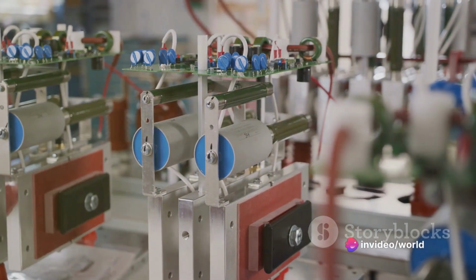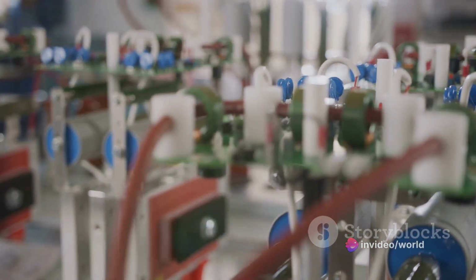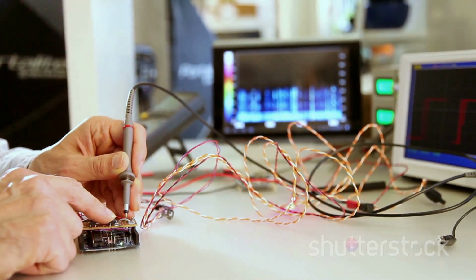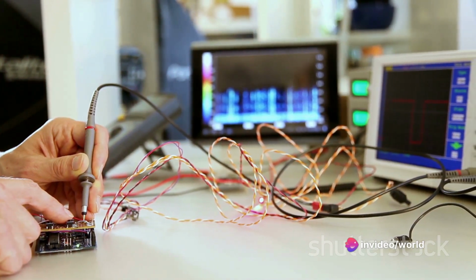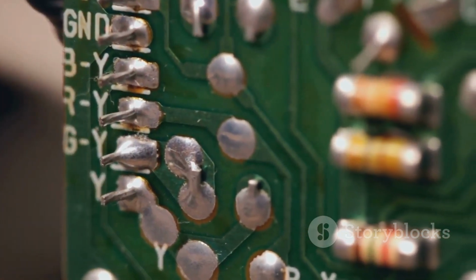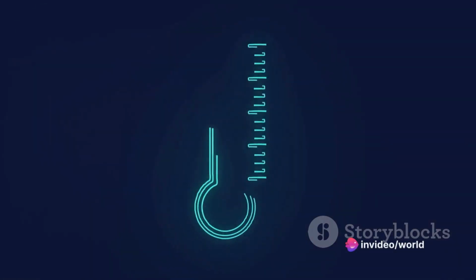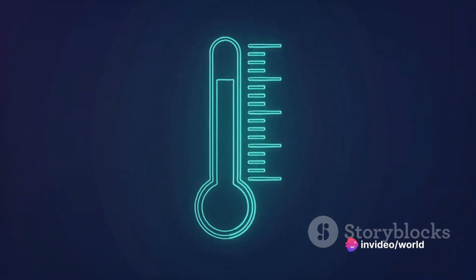Next, we have the capacitance tolerance. This is the percentage by which the actual capacitance can vary from the nominal or stated value. The third property is the leakage current, which represents the small amount of current that leaks through the capacitor, even when it's fully charged. Then there's the equivalent series resistance, or ESR. This is the sum of all resistances in a capacitor's equivalent circuit. Lastly, we have the temperature coefficient. This property defines how the capacitor's capacitance changes with variations in temperature.